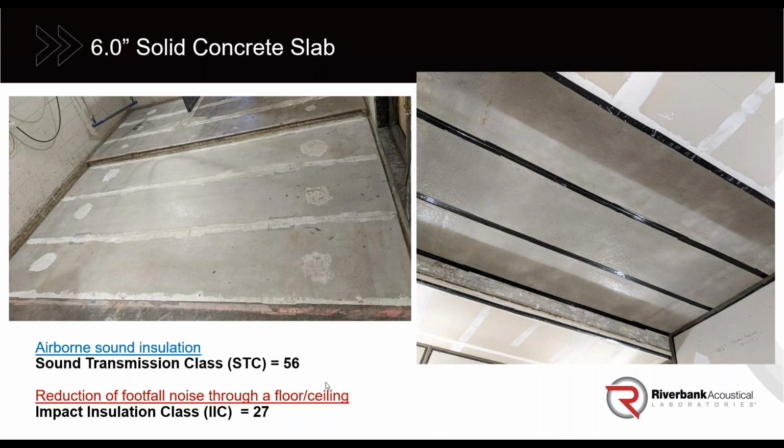However, even though you get STC for free, IIC is a big consideration. Without any floor covering, you would have an IIC of 27. So if you had a polished concrete floor and an exposed slab in the room below, that's a very poor IIC performance, 27.